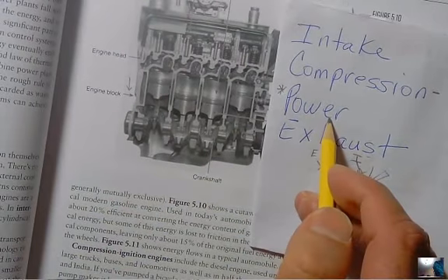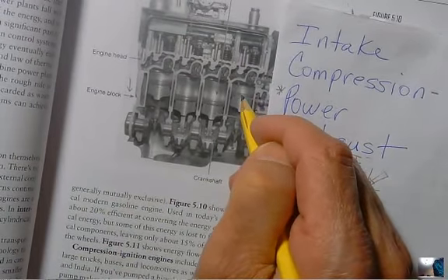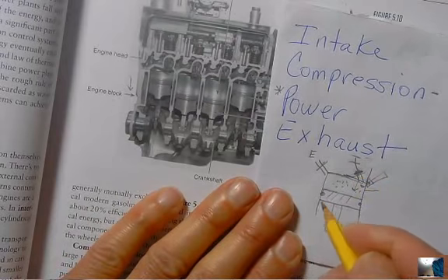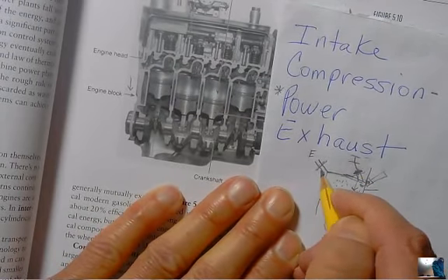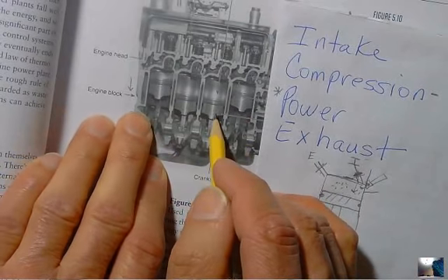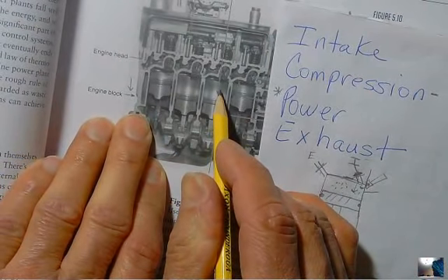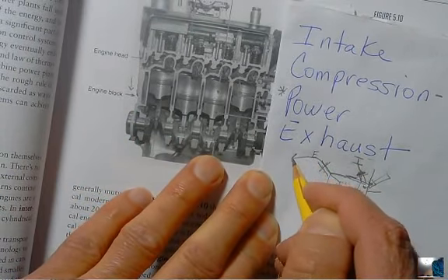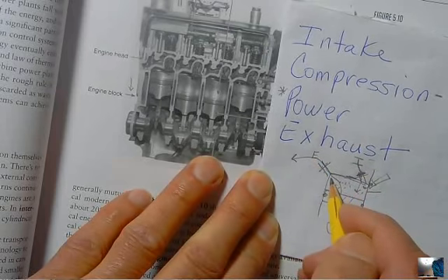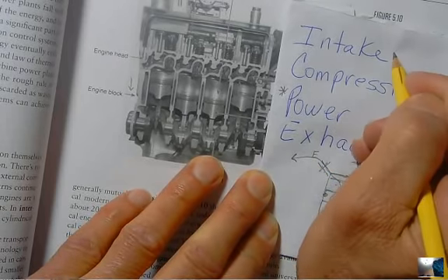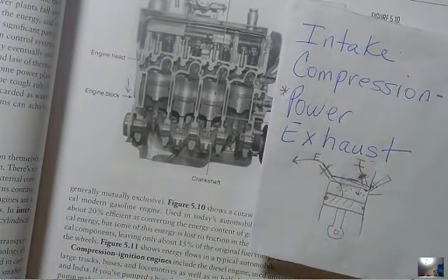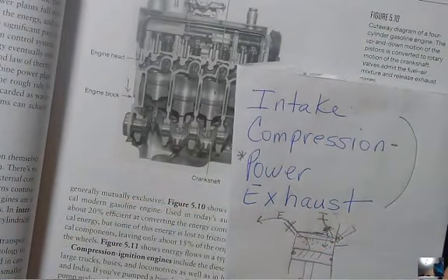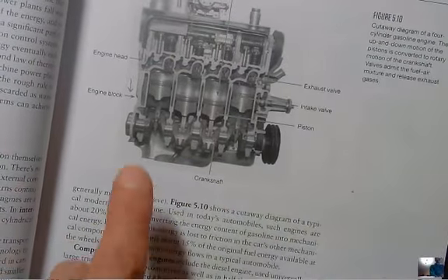After the power stroke occurs and it forces this piston back down to the bottom, the next thing that has to happen is the intake valve is closed off and the exhaust valve is opened up. And this time, when it comes back up again, instead of compressing hot air, it pushes out the dirty exhaust that just got burnt, and then in this closed up position, it starts the intake cycle all over again. So those 4 cycles happen over and over again, more than 1,000 times every minute in each one of these cylinders.